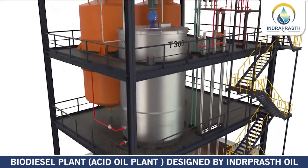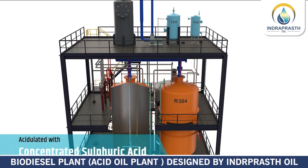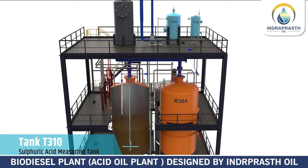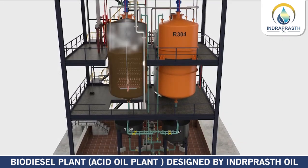The treated soap stock at 80 to 90 degrees Celsius is conveyed to the reactor R303, R304. In the reactor, the soap stock is acidulated with a calculated amount of concentrated sulfuric acid. After filling the reactor with soap stock, the acid is conveyed from the overhead tank T310 by gravity into the reactor. The mass is mixed well with the help of sparge steam through a copper coil in the reactor.